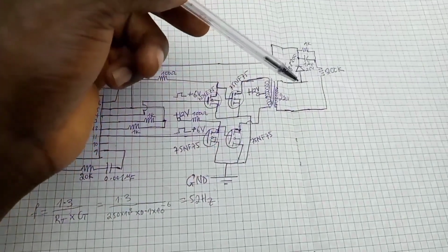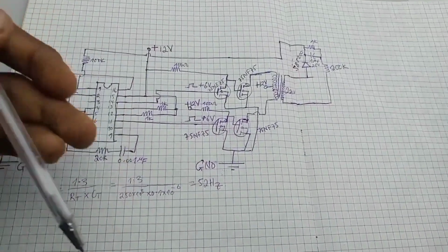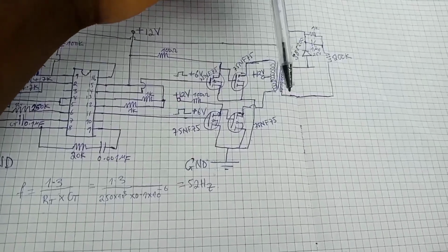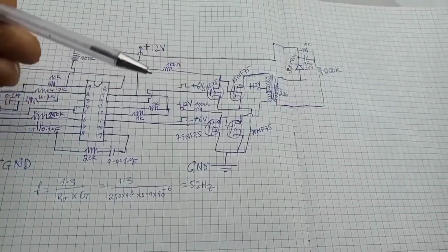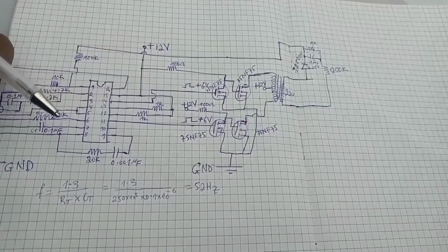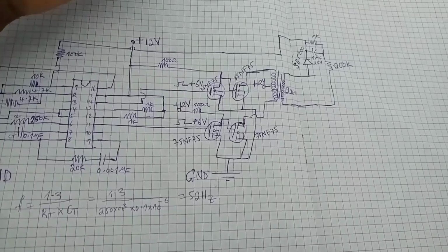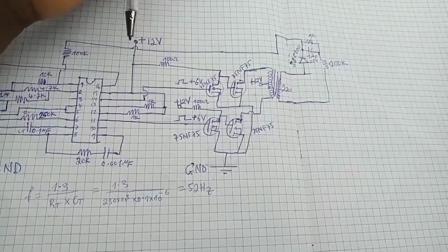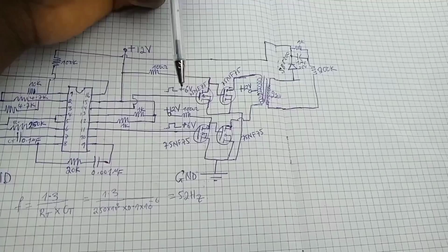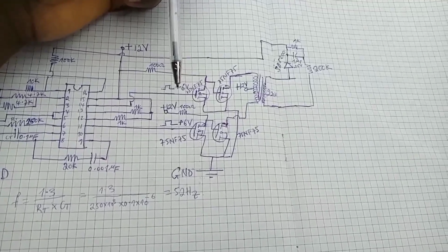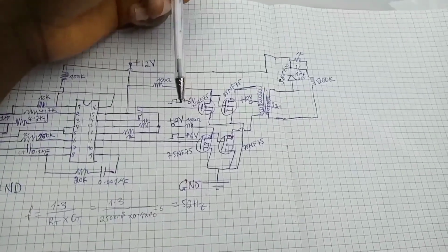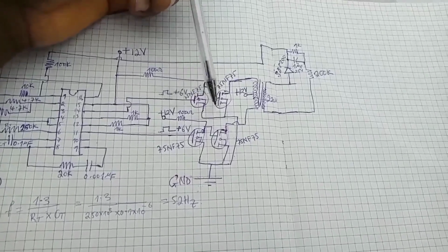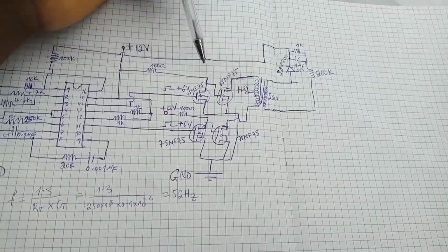Now in this circuit, this feedback permits such that when the voltage of the battery drops below a certain value, it permits to turn off the MOSFET, due to the fact that the voltage could drop lower than the threshold voltage of the MOSFET and could damage the MOSFET if the system is not turned off. And at that instant, the pulse width modulator will detect the voltage and will automatically turn off the circuit. So that is basically the function of the feedback loop.